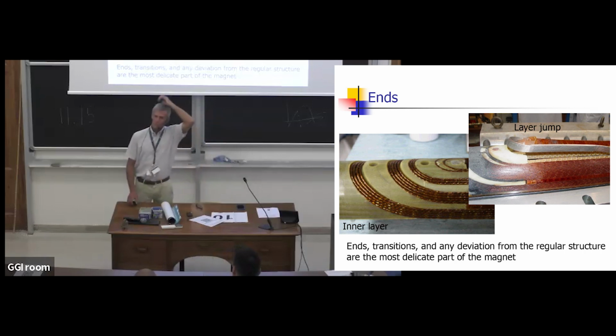Okay, so typically what happens is that you start off with a cross section, and then you feed that into a field program. You feed it into ANSYS or COMSOL. You feed it into custom programs, and then you get the results. And then you try and make sure that the stresses are okay, the protection is okay, and so on and so forth. I tell you, unless you understood what you're doing, there's no point in doing the numerical simulations. So you better understand the analytic before, because stresses can be wrong and protection can be wrong.